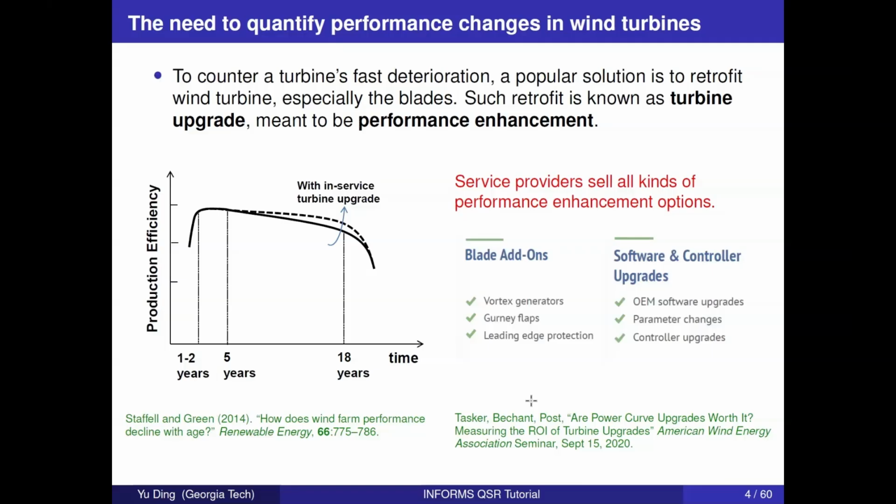You can see it is different from the bathtub type of reliability curve. Here, they only have a very short period of stable operation, the first 5 years. Initially there's a kind of burn-in process. And after that point, you can see a very clear degradation in turbine performance.